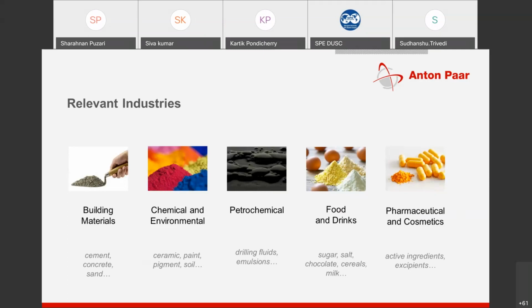If you have a complete blend of 10% finer, 10% coarser particles, and the rest in between, then it is called a good strength, early strength, high strength cement, which has an early settling time. So particle size control in the cement industry will give you different grades of cements.